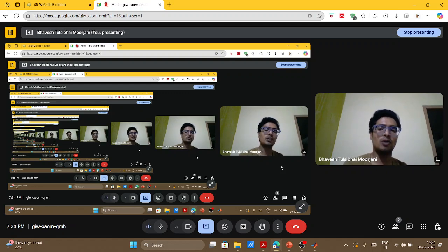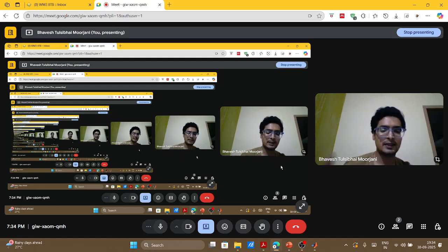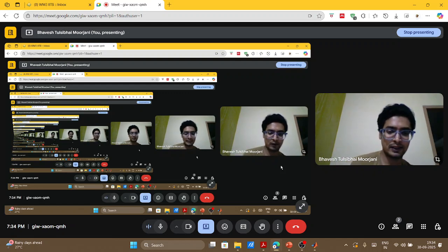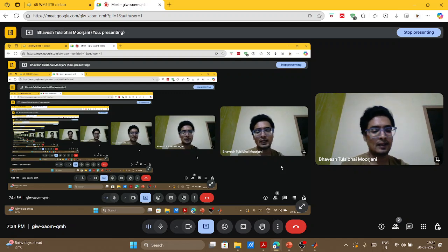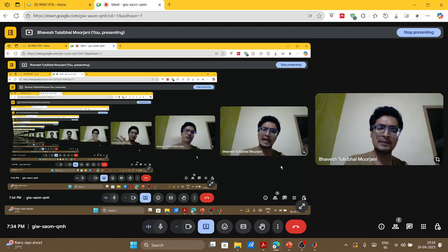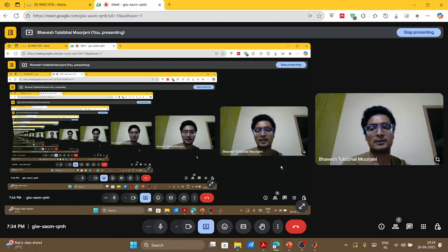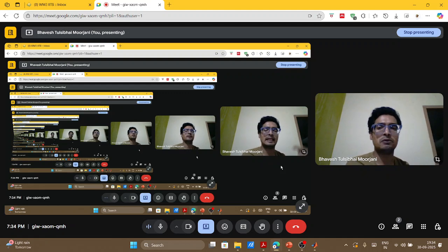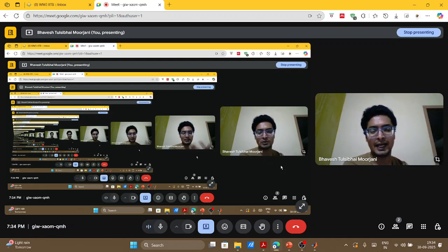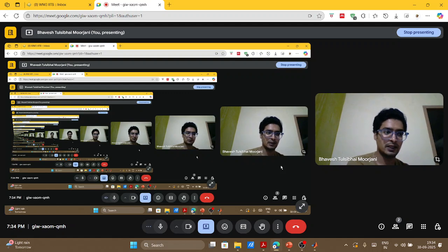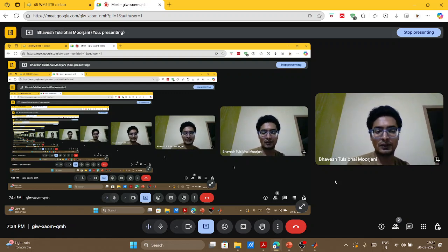So now let's say you want to automate this process. In that part we relied on the finite element method and solved the entire problem. But same problem if I want to solve with the help of the PDE modeler in my system, in that case you can run one for loop where your time is changing from 0 to your desired value or the steady state value, okay? For each time point you take out what is the corresponding value of q. So we had that equation, q is equal to, I think it was 10 to the power 4 into the exponential term of the time, right? So you know what is the value of q.